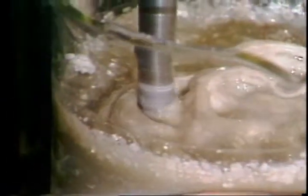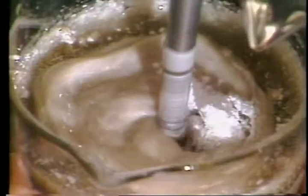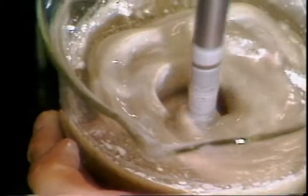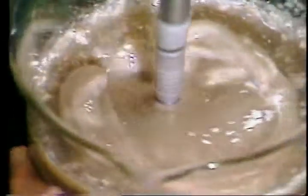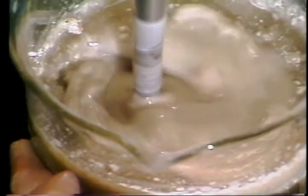Let's watch this. The first problem, too much viscosity, can be corrected with a couple of different chemicals. They're called dispersants. This bentonite has been contaminated with lime. We'll add a certain amount of a dispersant called chrome lignosulfonate. As it's mixed in, it causes the bentonite particles to release the water they've soaked up, sort of like wringing the water out of a sponge. Now the water is free and suspending the mud particles again. This and most of the other freshwater dispersants cause the chemical reaction that reverses the action of the contaminants.